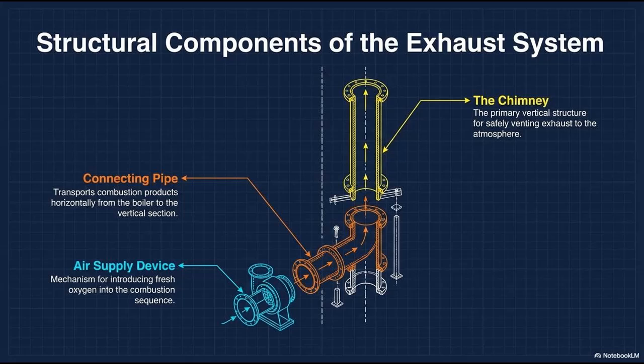It is the most critical question a homeowner can ask, because knowing exactly how your heating system inhales brings us directly to that invisible tug-of-war you mentioned at the start. Exactly, because having a Type B appliance, the one that exhales outside but still breathes the air in your house, has suddenly become incredibly dangerous in modern, newly renovated homes. It is a crisis entirely of our own making, and it is driven by the sheer ravenous math of combustion.